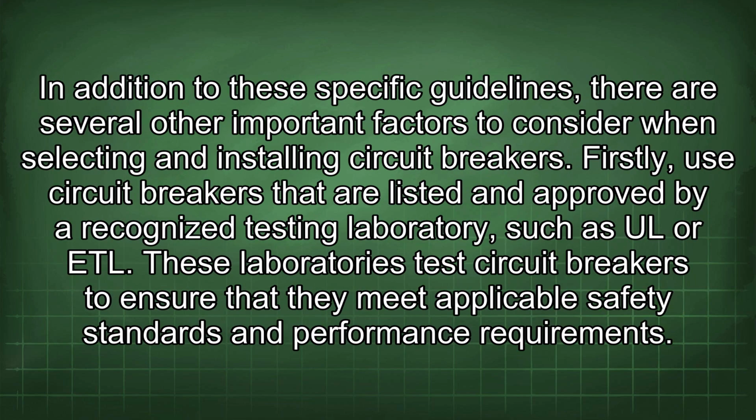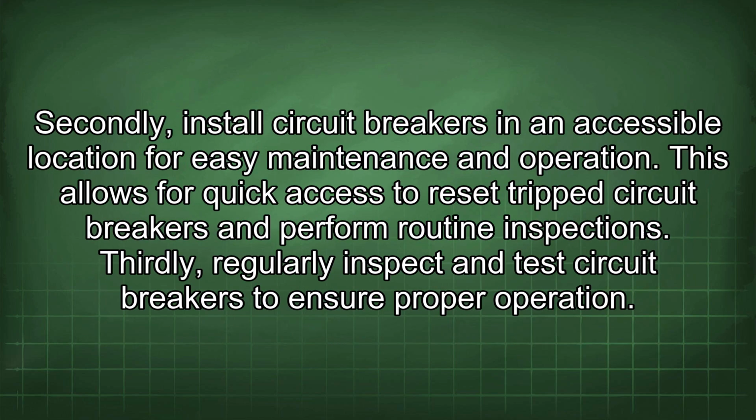In addition to these specific guidelines, there are several other important factors to consider when selecting and installing circuit breakers. Firstly, use circuit breakers that are listed and approved by a recognized testing laboratory such as UL or ETL. These laboratories test circuit breakers to ensure that they meet applicable safety standards and performance requirements. Secondly, install circuit breakers in an accessible location for easy maintenance and operation. This allows for quick access to reset tripped circuit breakers and perform routine inspections.